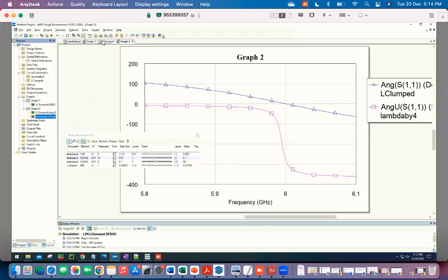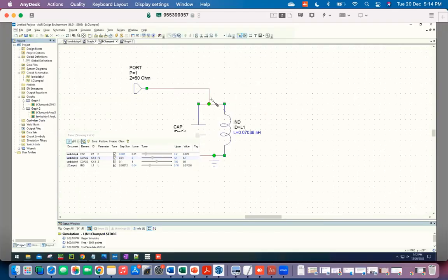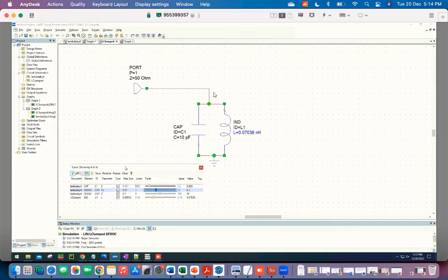Now, these kind of things can also be done here. If you have a lumped element parallel LC oscillator, the quality factor for a circuit like this, which is directly coupled to the 50 ohm line, is only dependent on this 50 ohms, the frequency, and this capacitance. So it's impossible to make very high Q resonators of this type with the circuit, because then you need capacitance to be huge. Right? If you want 100 times more Q, you have to make the capacitance 100 times larger and the inductance 100 times smaller. So then those values will become unreasonable.